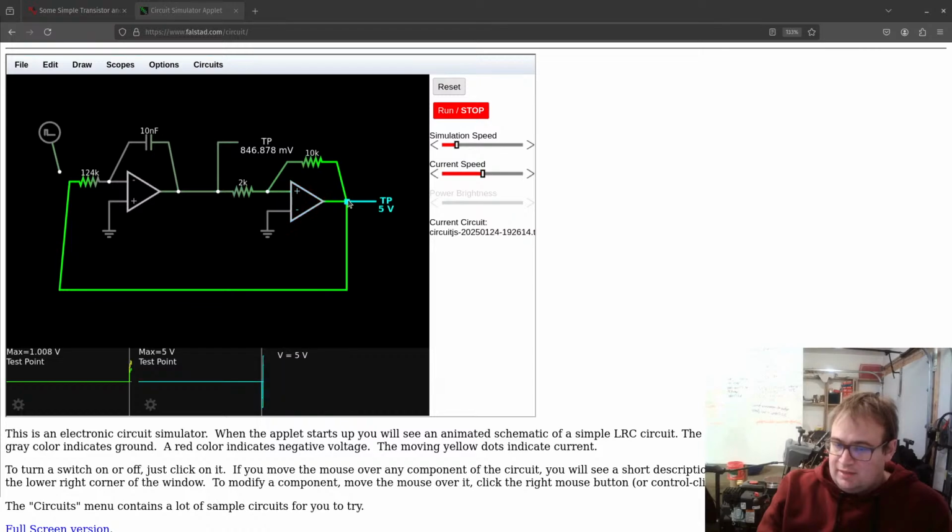To make it not have that, we will start having a negative voltage here, which will start shoving the output down because it's the non-inverted input, until such time that these two are equal again, and it will never get that way until this goes to -5 volts.